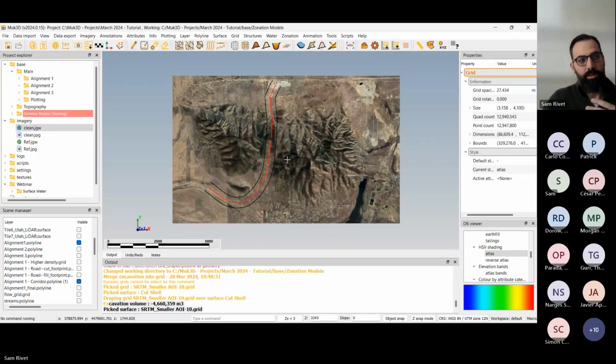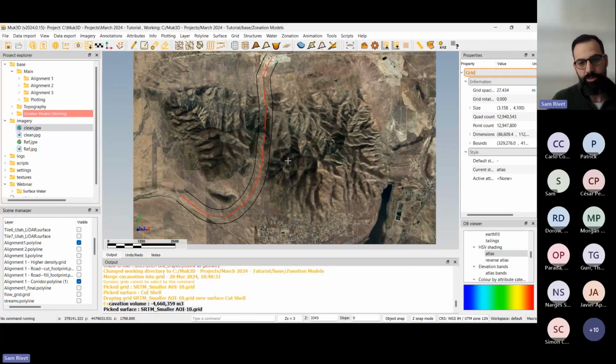As well, before you construct this road, you're going to have to strip it. So I'm not exactly sure the composition of this terrain, but I'm going to assume there's a level of topsoil that I'm going to need to remove. And you want to work on a topographic surface that's going to reflect reality. So the reality is you're going to have to strip any construction area. So within the footprint of your road, you're going to have to remove that topsoil and stockpile it and use it later. So what I would recommend, because we don't know where our road is yet, is you create a box or a polygon out of your corridor, and then you drop your topographic surface by the amount of topsoil you expect. So in this case, I'm going to say 30 centimeters of topsoil.